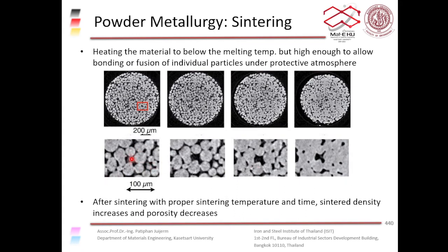So if you look at this picture here and this picture here, it is from the same place. You can see this hole here, right? It developed into this hole, into this hole, into this hole. So it is the same place in the material, and you can see that in this picture you have a lot more darker area than this picture, right? That means you have less holes, less pores, less voids in this picture.